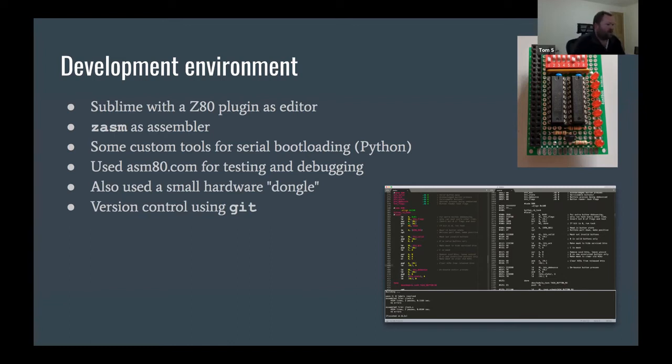As I've mentioned a couple of times, I had a few little tools that I use for serial boot loading. So basically just working in concert with a little piece of boot loading code, which would receive a little command to say, start loading some data at X address, and then you just start dumping binary data over the serial cable, and it will place it all into RAM.